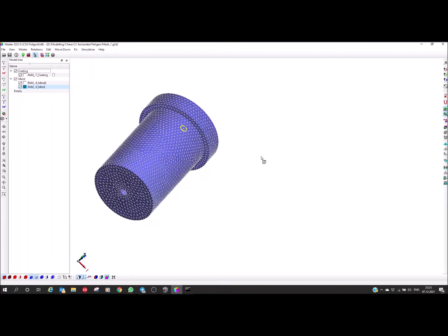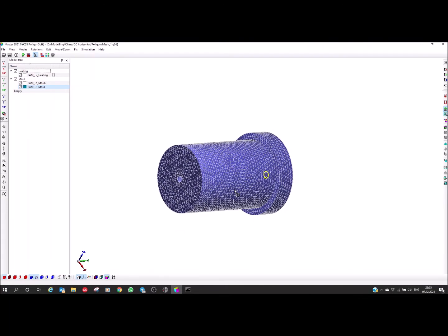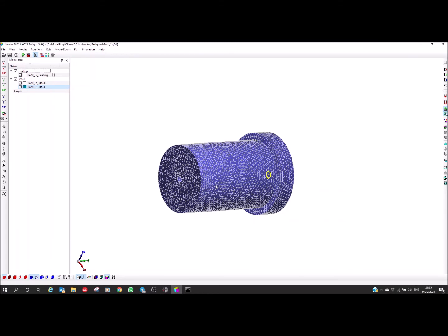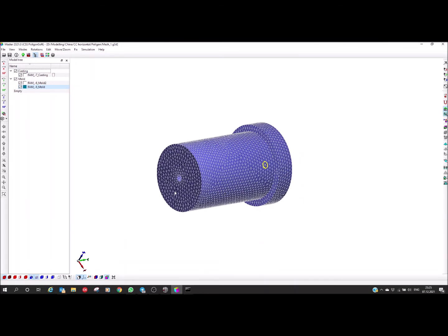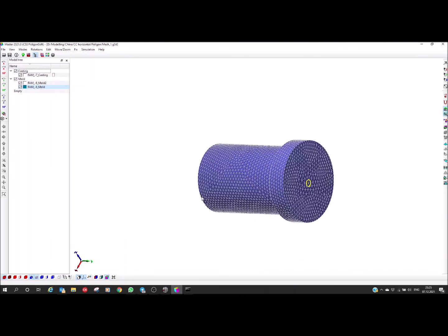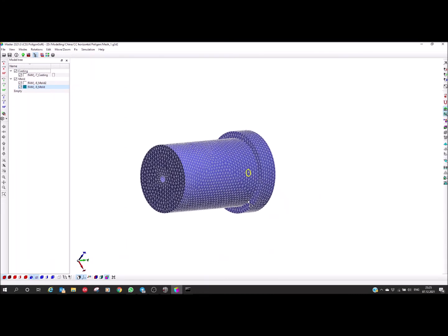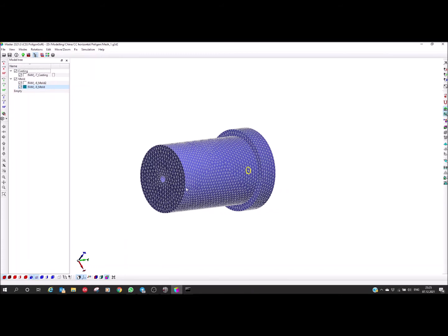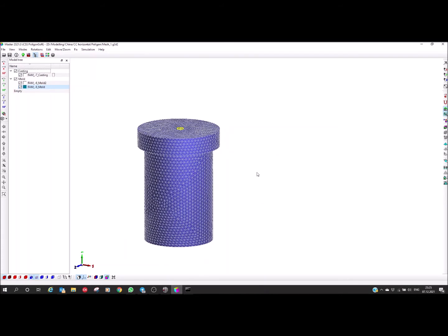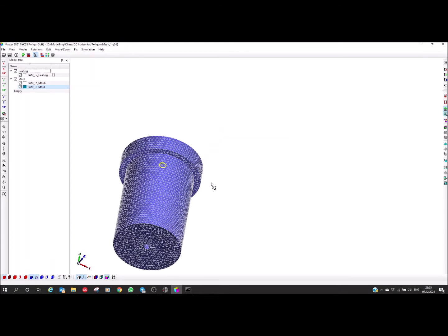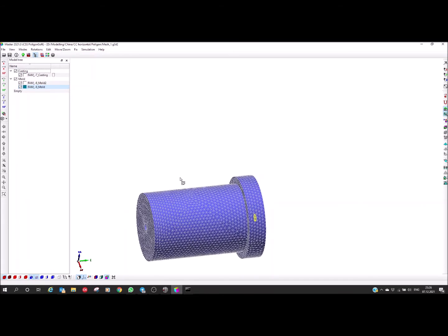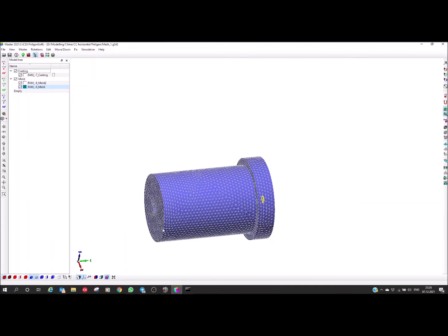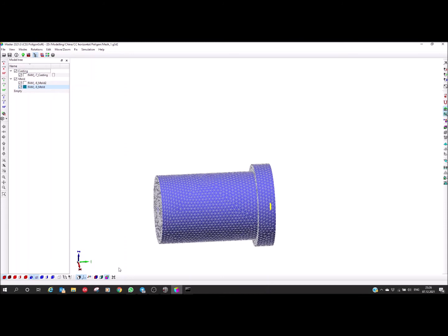But in horizontal centrifugal casting the centrifugal force is much higher than gravity, so we can simulate this type of centrifugal casting, but we need to orient our geometry like here and set up the rotation axis like this along the y-axis, but we will simulate only solidification. It doesn't matter that our gravity vector has the wrong direction.